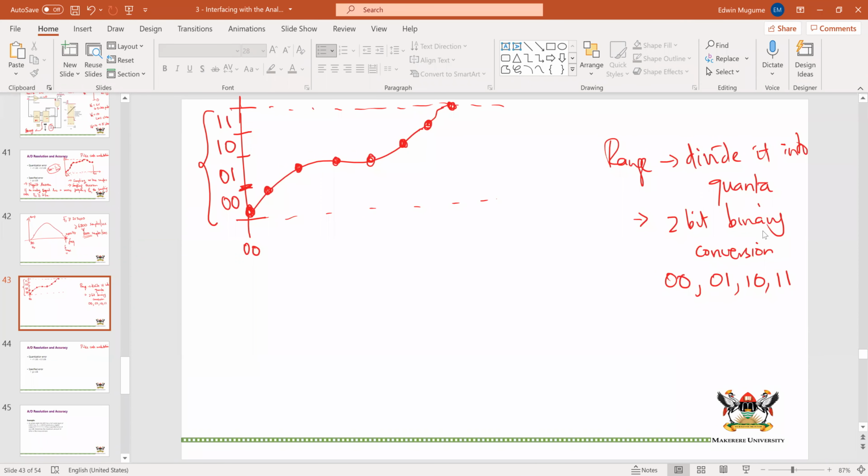So you have a sampler, it takes a sample and compares it with your quanta and encodes it into some digital signal. This sample here is still in the same range, so I'll call it 00. That sample here is in 01, so I'll call it 01. That one as well, even this one, and that one is now in 10.